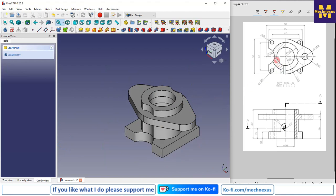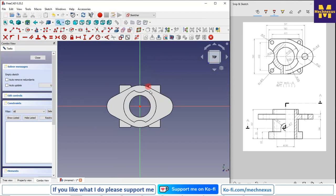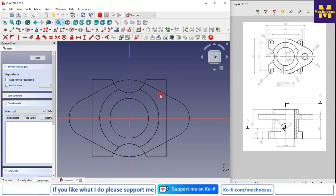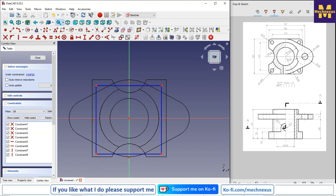Now we will create these 4 holes. So for this I will select the face and I will create a sketch. I will switch to the wireframe. So when making this type of a hole, it is better to create first a rectangle and make it a construction and then make it symmetric.